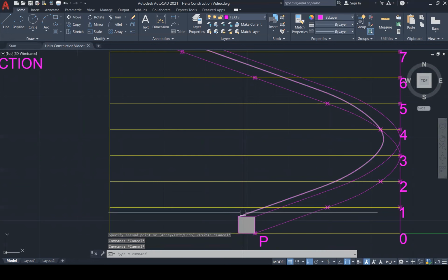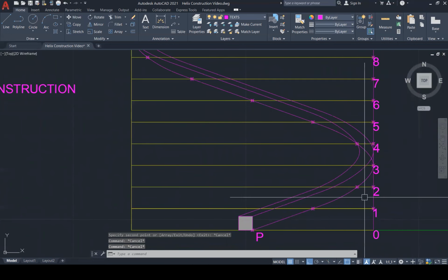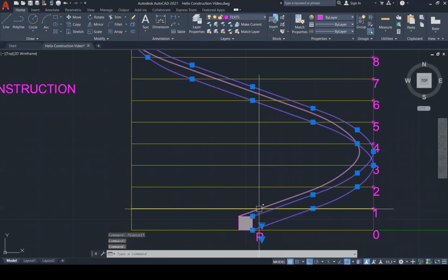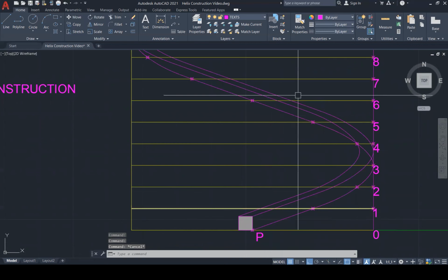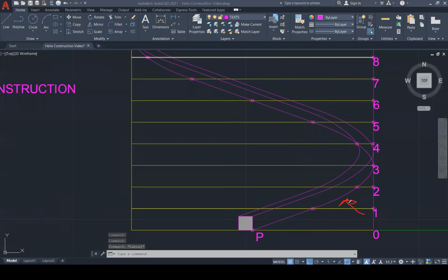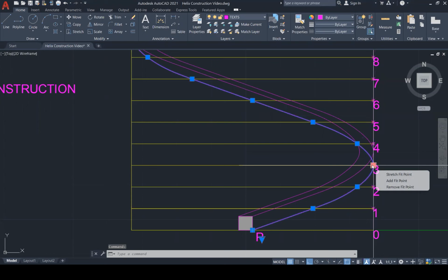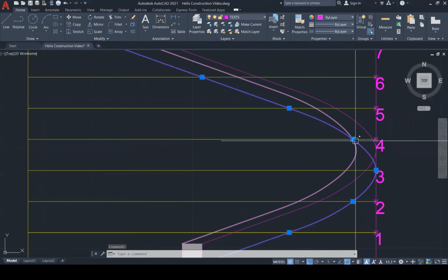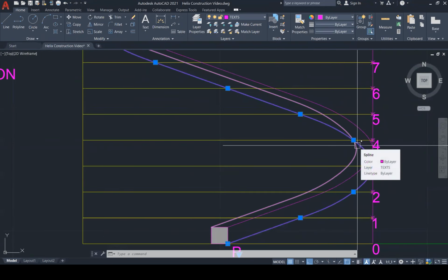So that's the thickness there. And let us see so far, because these are the three lines that I'll be seeing, 1, 2, 3, when I'm looking at it from this face, right? I'm going to be seeing these three lines. I'm not going to be seeing this line in here that's going to be hidden. So I'm not worried about that right now. Just dealing with what I can see to understand this. So this is going to be right here. And you look, this goes into here. And then at this moment, this line disappears and it goes behind here. So that means this becomes a hidden line.